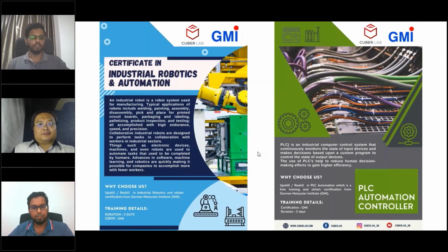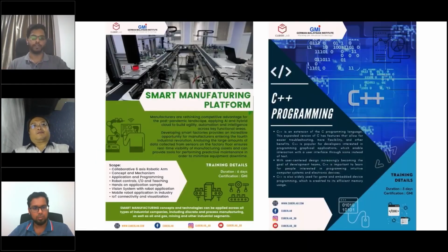Sure. Okay, vision system, there's a lot of types. We call it either vision sensor or vision system. With a vision sensor, we basically just teach it to make a decision such as pass or fail according to the color, shape detection, size detection. It just gives a pass or fail only. A vision system is more advanced than that, and it has more tools inside it for object recognition, measurement and tool orientation, all those things, and it gives data as output. So there are two types of vision.